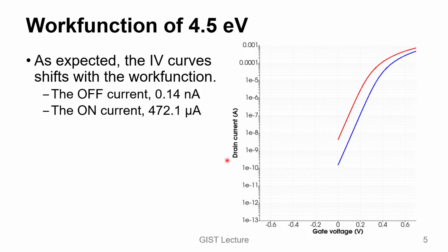One is work function. What is the role of work function? As we have seen in our previous lectures, in this semester, our structure does not consider the proper internal structure of the gate stack. The gate stack contains many layers for high-K, and also we have to introduce the work function metal and tungsten film.